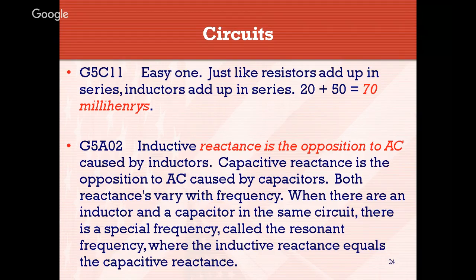They're tuned circuits, which means that when you transmit on a particular frequency, those cans are tuned in such a way that they will block all frequencies except what they're allowed to pass. So when it is resonant, it will pass the frequency that you're tuned into. So just something to keep in mind.